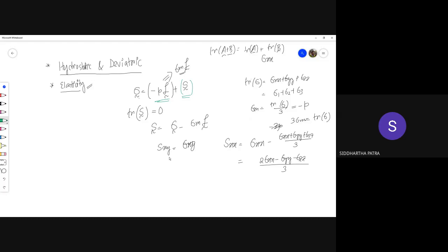Or when you are talking about a little bit of plasticity that a brittle material has, we probably have to talk about the hydrostatic part as well. Now, when it comes to metal plasticity, as has been shown by different authors, we can solely rely on the deviatoric part. The hydrostatic part has a very small role to play.